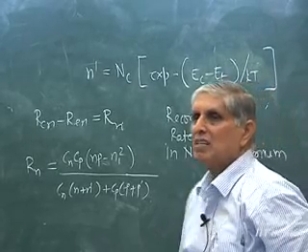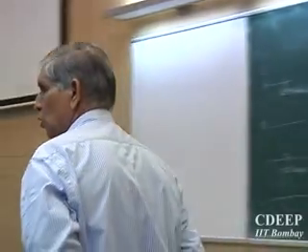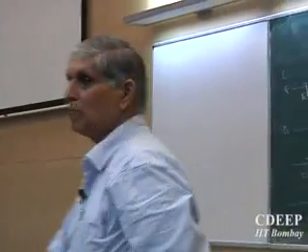How much will be Rn in equilibrium? 0. In equilibrium, are you getting 0 from there? np is equal to ni square. As soon as you are in thermal equilibrium, np is equal to ni square, Rn goes to 0. So capture rate is equal to emission rate.